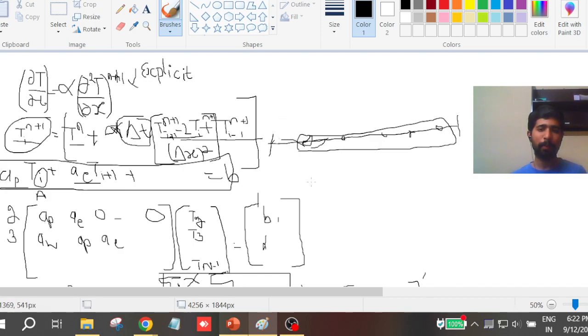So if the wave propagation speed is very fast, then the delta t should be very low. Otherwise what will happen is that, if you give a kind of pulse here, and you select delta t very high, delta t is equal to 0.01. Now assume that the velocity is very high, at delta t is equal to 0.01 the wave directly reaches the middle of the domain, whereas you are still at the second grid point.